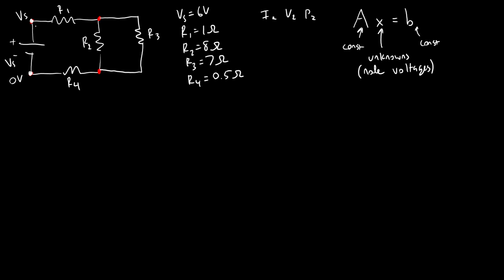We can just eliminate these 2 nodes right off the bat. Again, because we know that the ground node is only 0 volts, and since all we have connected between these 2 nodes is the voltage source, we know the voltage there is Vs. So we are going to define our other 2 nodes.